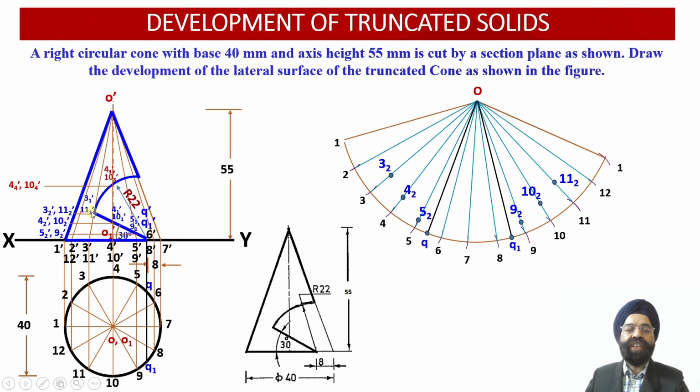So now the circular cutting plane points we have marked as red color points, whereas the straight line points of intersection we had marked with blue color. So now onto the slant generators O4 and O10. This is O10, this is O4. Again 2 points of intersection here we are going to plot corresponding to the radius O dash 4-4 dash and O dash 10-4 dash over here. So the corresponding points 4-4 and 10-4 they have been obtained onto the slant generators O4 and O10 over here.